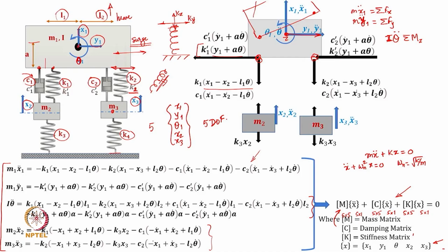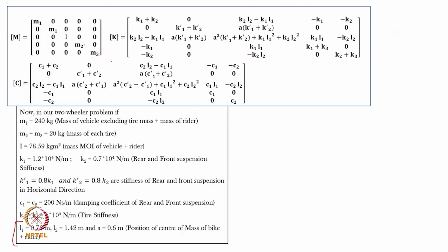For coupled pitching and bounce motion of a car body, we discussed that if they are decoupled, you can very easily get straightforward natural frequencies in pure pitching and pure bouncing mode. So, all of that is fine, but when you have many degrees of freedom, you have to solve the matrix equation, and there are standard numerical approaches to get the eigenvalues from this equation. One other way of getting the eigenvalues is to use standard commercial software, which we will discuss shortly.